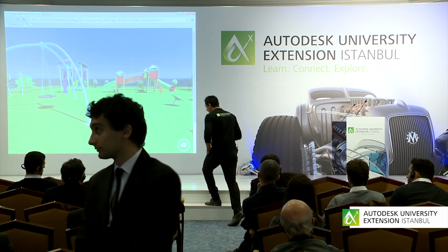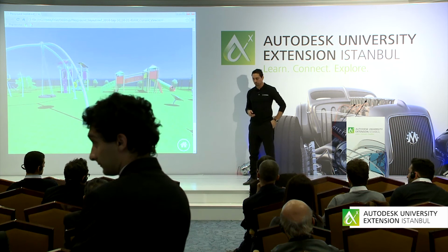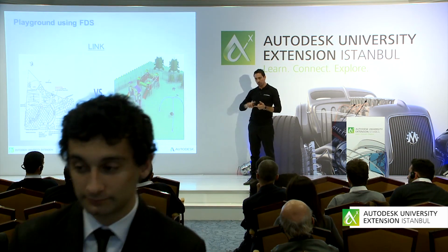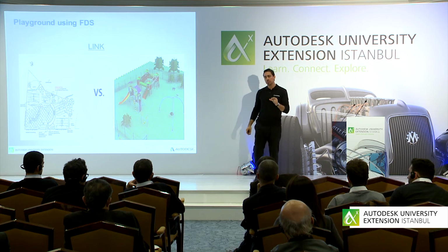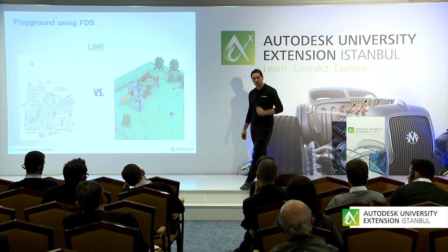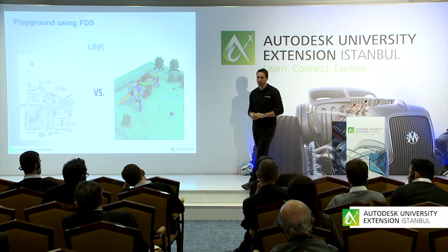Yeah. Okay, so you want to get the lengths of all the pipes, the cuts, and the bill of material of each pipe layout. There is something inside of Inventor that can do maybe a little bit of it, but you need Plant Design Suite to do that.